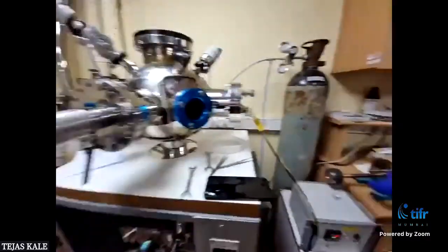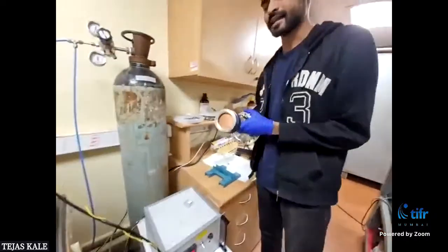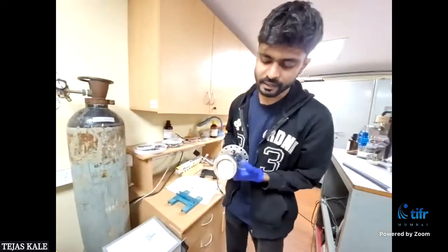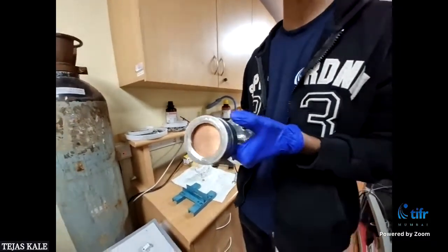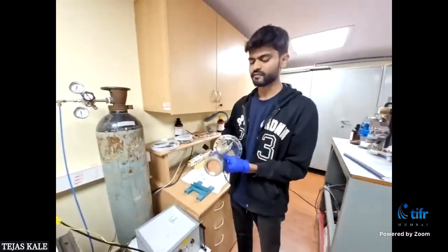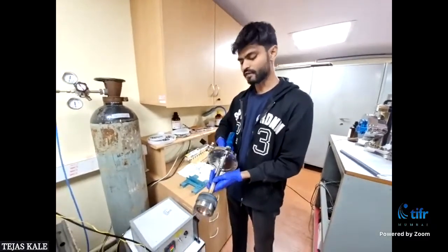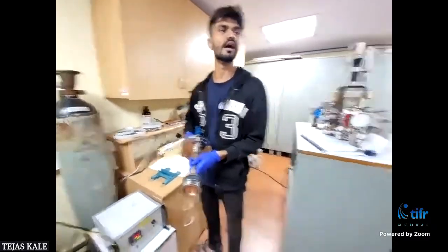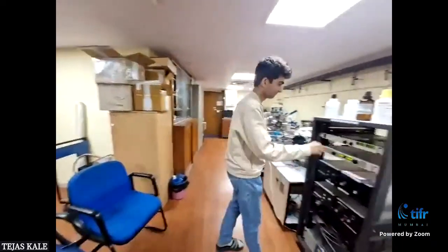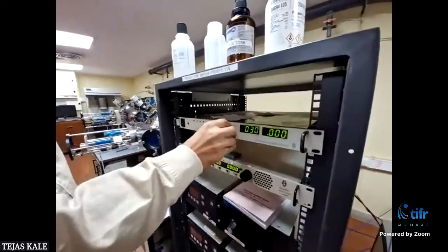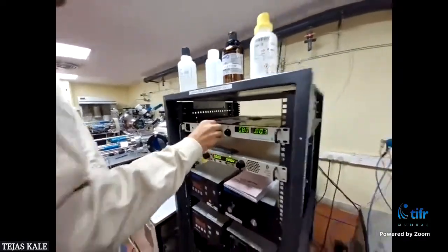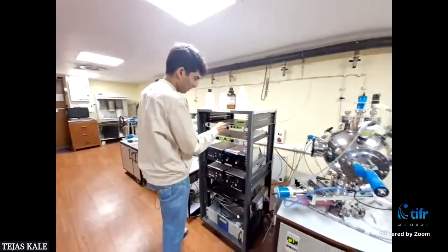Here is the sputtering gun, and it has the copper target material, which you can see on the top. This copper will go from the target to the substrate when we apply the voltage. So now I will tell Meet to apply a voltage. You can see behind there is our power supply. We have already set how much voltage we require and how long we are going to deposit this film for.